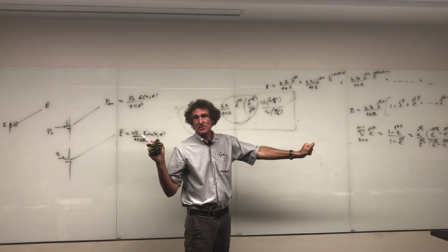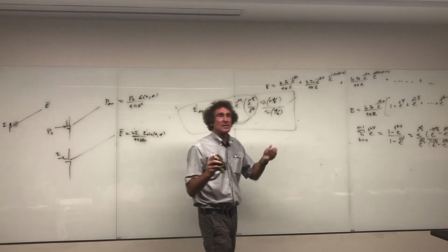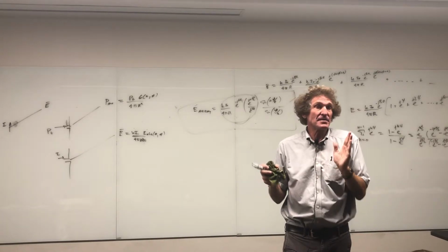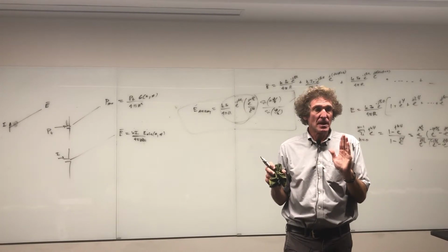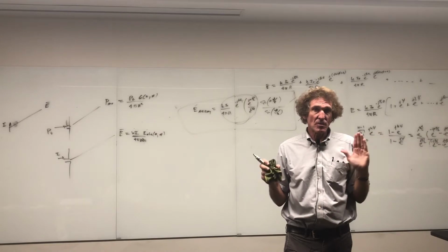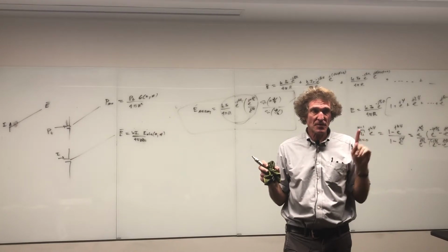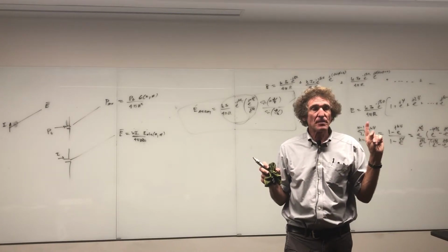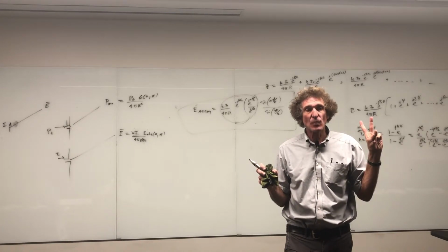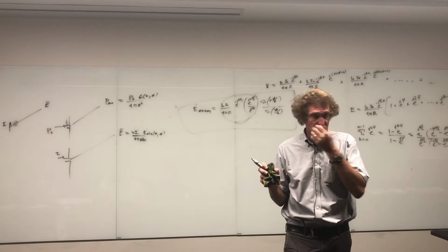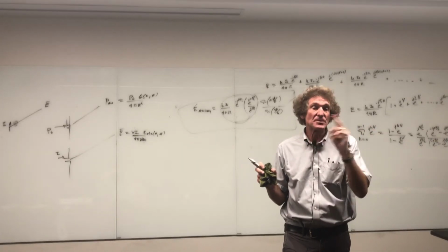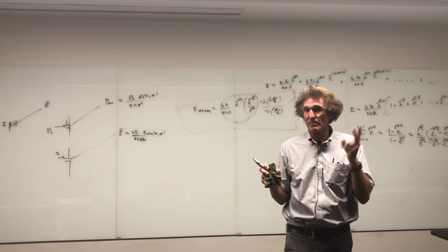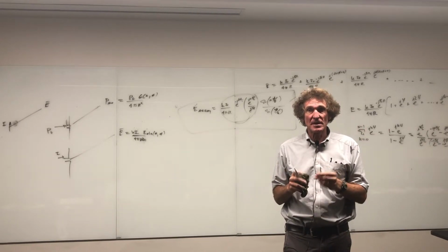Got that? That should make sense to you, right? Each element has an electric field of a certain magnitude. If you got all of them in phase, you should get n times that field. In effect, you do. It's a one-dimensional array, so you're going to have n times the maximum electric field of one of these. But the power goes up by a factor of n squared times E. The power density, I should say, will go up by a factor n squared, which is important. That means the arrays themselves magnify the peak power density by n squared.